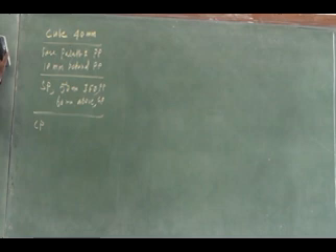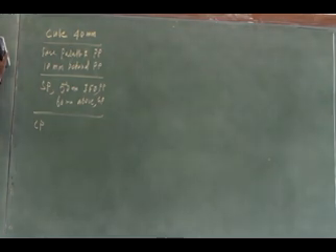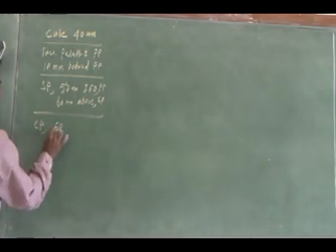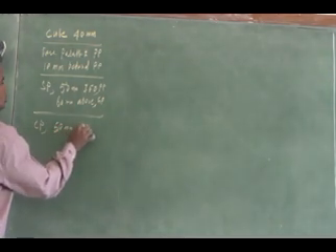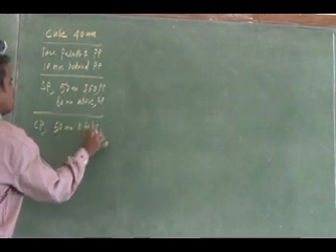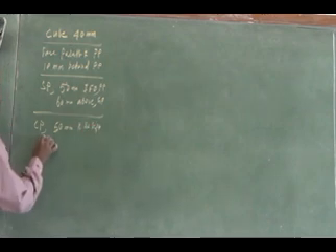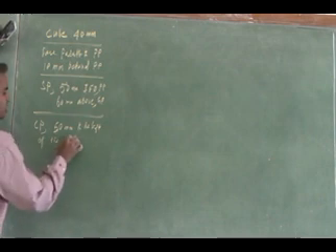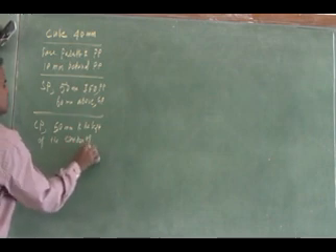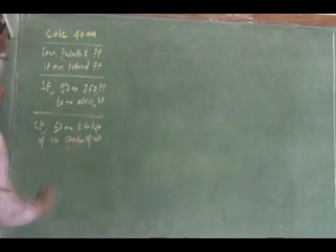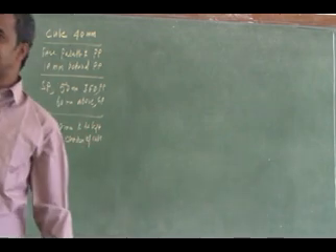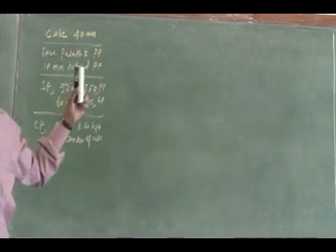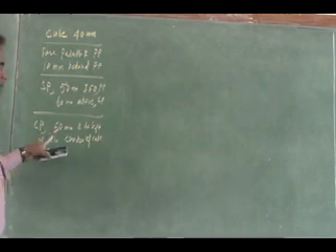50 mm to the left, which is the center plane, 50 mm to the left of the center of the cube, right? So you have to mark the center of the cube. From the center of the cube, the center plane you have to draw to the left at 50 mm